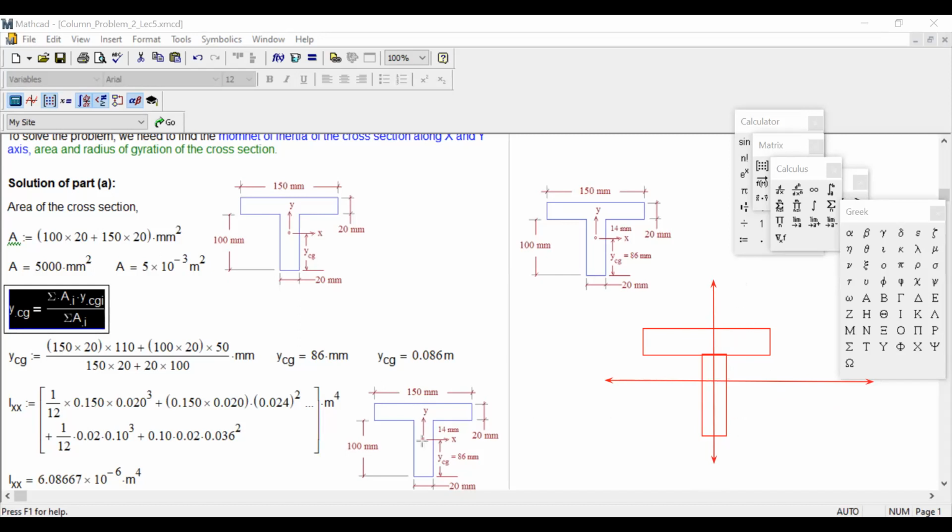So in that case, the I we use in the column is with respect to the CG of the cross section. So we need to know where is the CG of this object, of this cross section. So how can we figure out the CG? So this is our cross section. It has all the geometry.